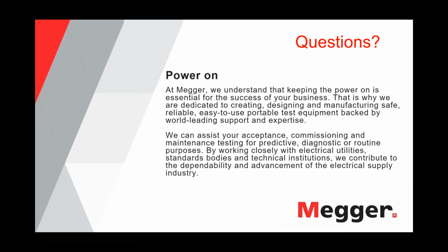All right, Javier, is there a minimum and maximum cable length to perform VLF and TD tests? Okay, well, regarding the minimum, maybe 82 feet will be the minimum length of cable, because it doesn't make sense to do a tan delta test on a shorter cable. I can just change the cable and that's it. Regarding the maximum length, it will depend on the capacitance of the cable.